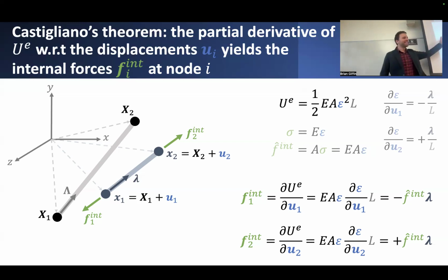What happens if this element rotates 90 degrees? Now, if we said these forces have to act parallel to the original axis, then effectively those forces would be acting in a direction perpendicular to now the deformed axis of this member, which makes no sense. In order to account for that, we have to now put the forces always acting along an axis relative to the deformed configuration of the element. So that should make good sense.